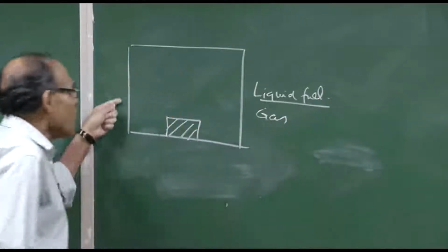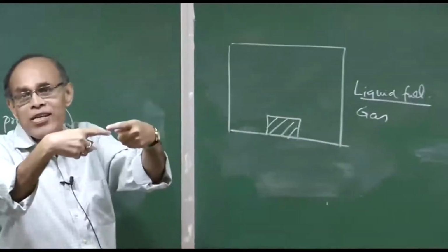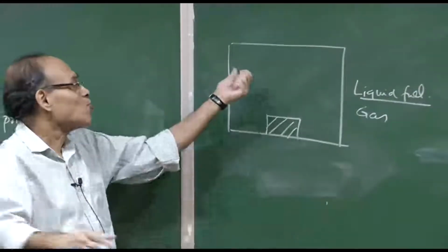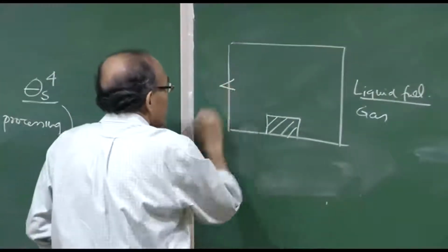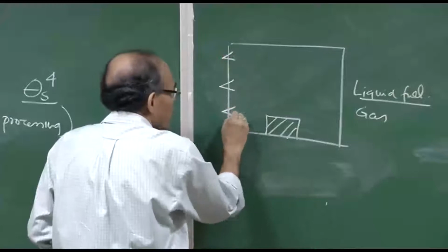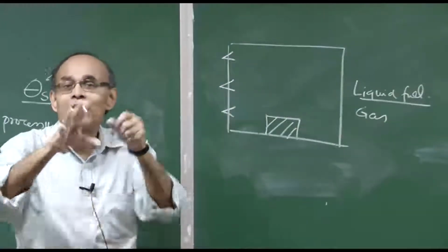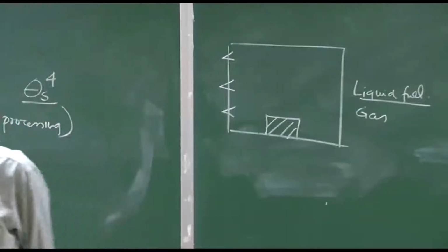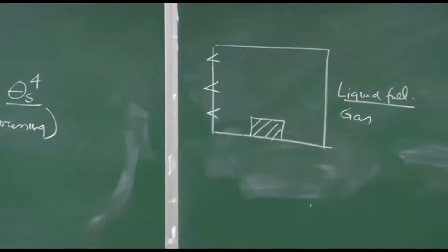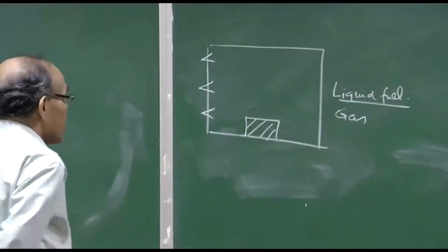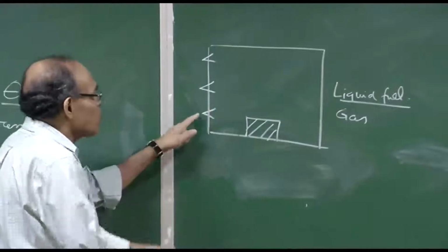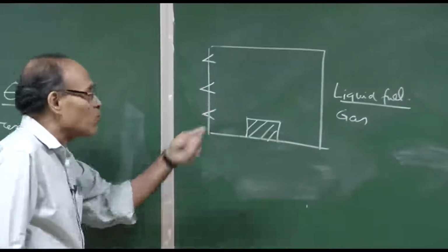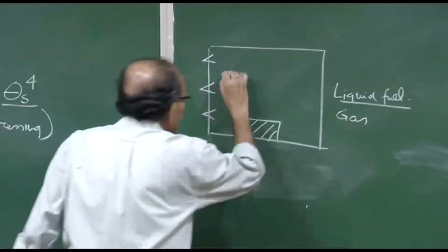These furnaces could be either gas fired furnaces or liquid fuel fired furnaces. So we can introduce blast furnace gas and combust it with oxygen, and that is how heat is going to be liberated. There may be burners here, or you can introduce some liquid fuel, petroleum or a similar kind of furnace oil, for example, and then it can be mixed, atomized with oxygen, burn in the furnace and produce the heat itself.